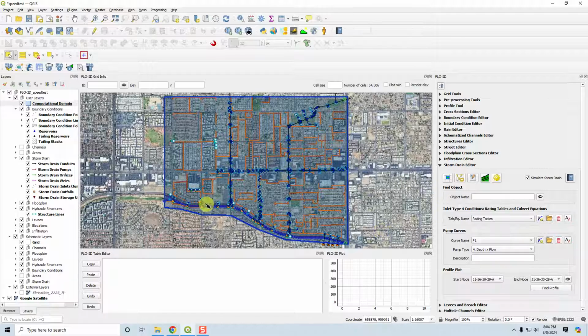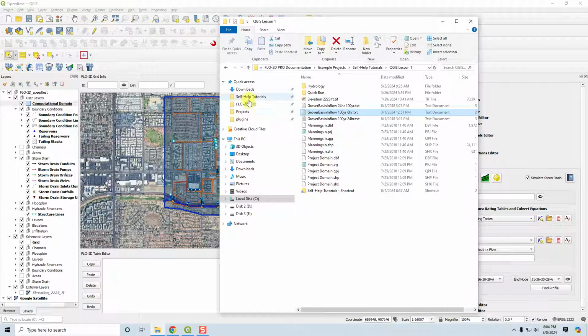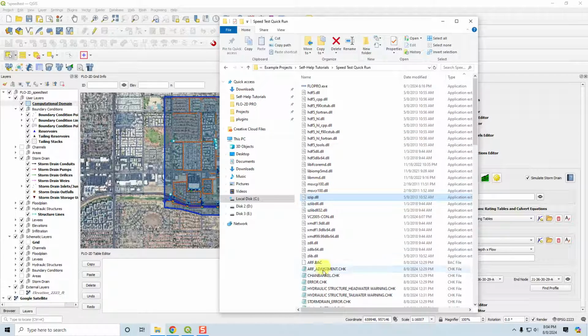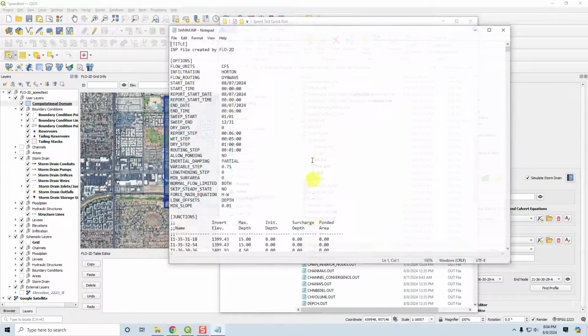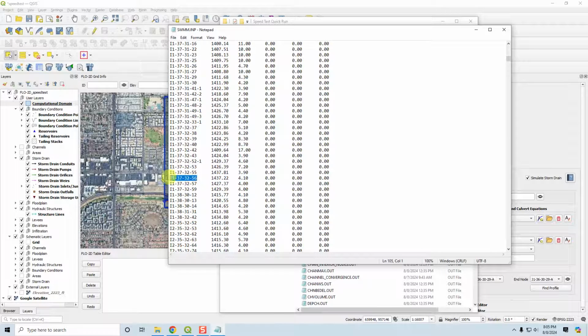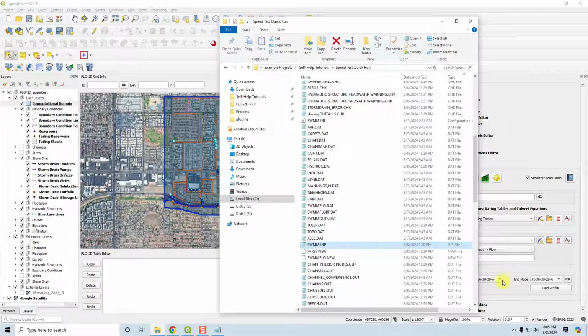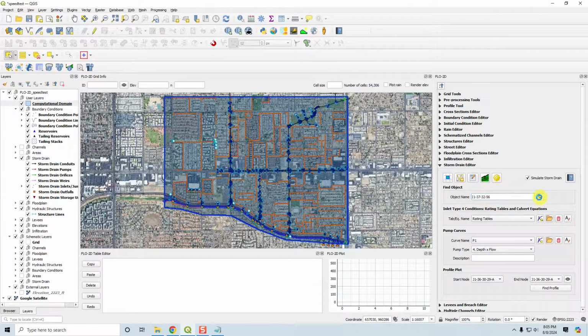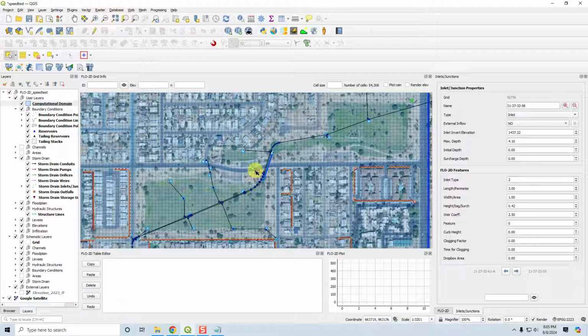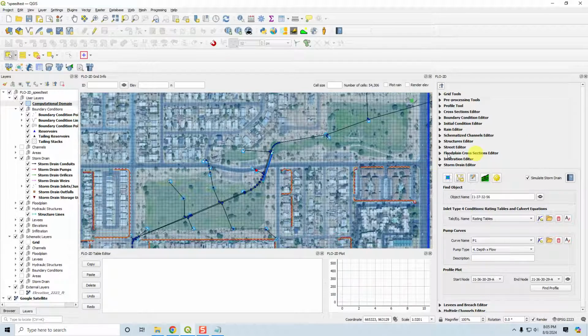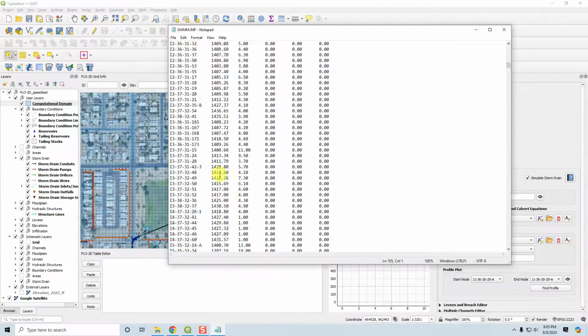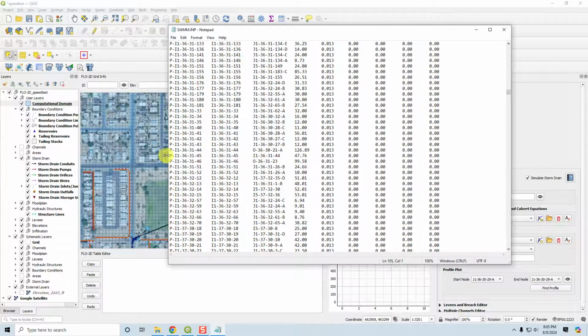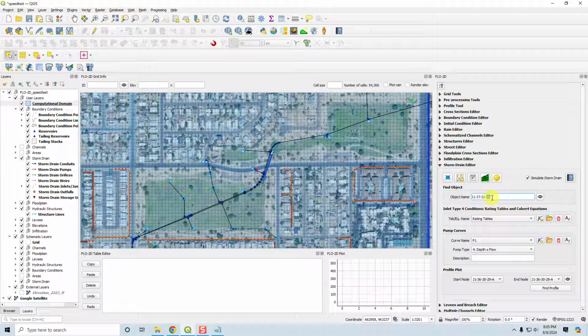Oh, one cool thing he did that I really like, and I will show you because it's really helpful. Let's grab our swim INP real quick, and let's just grab a random feature and copy the feature name. And if we put that right here, we can open any object. So it'll zoom to the object and open the object editor. And so let me close that editor real quick. Let me grab another one. So that was a junction. Let's grab a conduit. Sorry, I'm having problems with this because it's a notepad, so you can't just triple click it to select it.